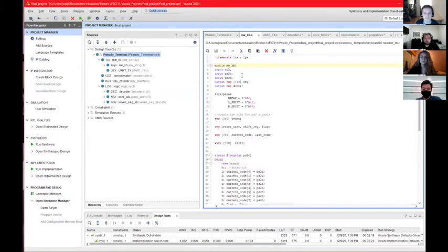So what I ended up doing was stripping it down to the bare basics of what it really needed to do, so that we could troubleshoot it better, and also make sure that it was delivering the results that we wanted. So what it does essentially, it takes in the PS2 clock, the onboard clock, the data stream, and it outputs a key code and a tick indicating that it's done, ready to be read by the UART.